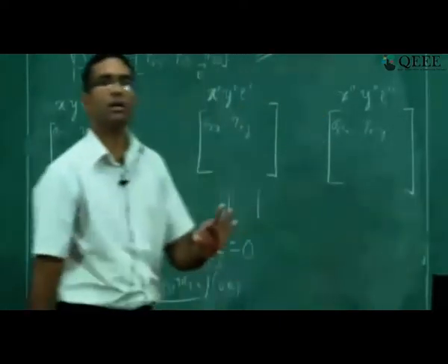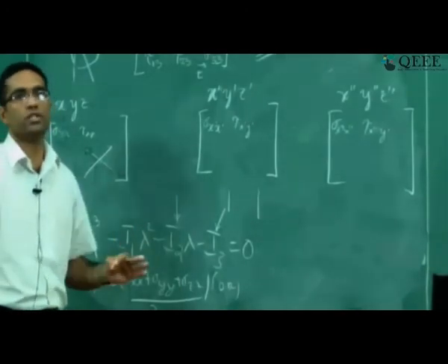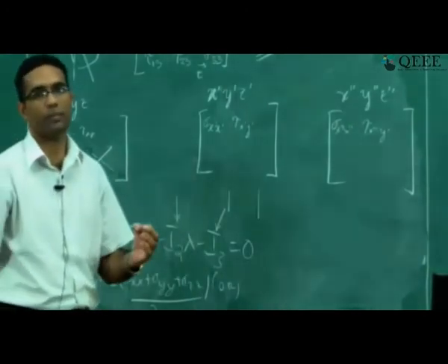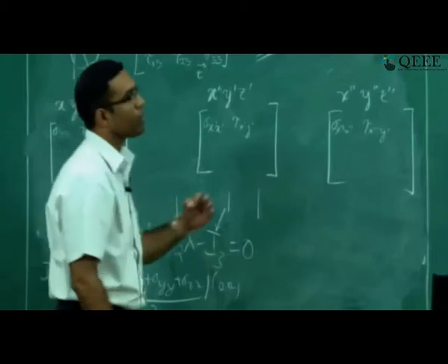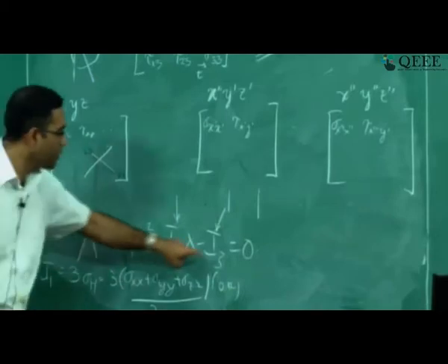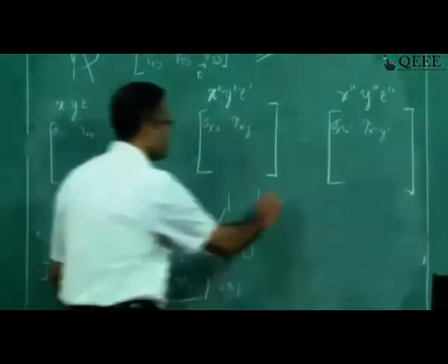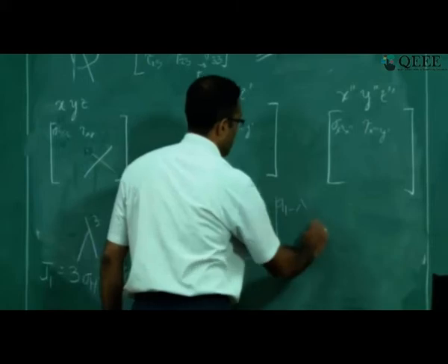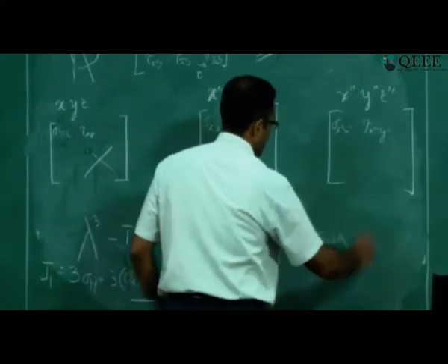These three numbers don't change no matter how you rotate the coordinate system. So this is very important. Whenever you want to find the principal stresses, remember you have to solve this characteristic equation first, because that is what gives you three different values for lambda, which are essentially the principal stresses. You don't necessarily have to go through sigma 11 minus lambda, sigma 22 minus lambda and take the determinant.